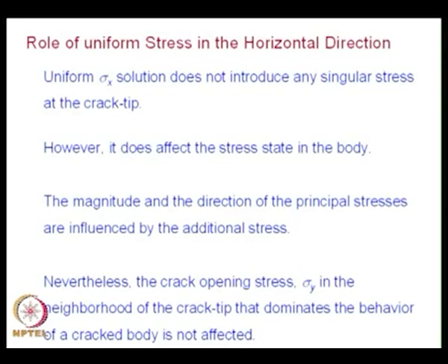So, in the initial stages of fracture mechanics development, if you are confining your attention only to the close vicinity of the crack tip, use of the term sigma x really does not affect, because the crack opening stress sigma y in the neighborhood of the crack tip that dominates the behavior of a cracked body is not affected. So, from that point of view, it is justifiable, but you have to keep in mind that after looking at the generalized Westergaard equation, none of these solutions are accurate. You have to go for multi-parameter solution for any problem of practical interest.